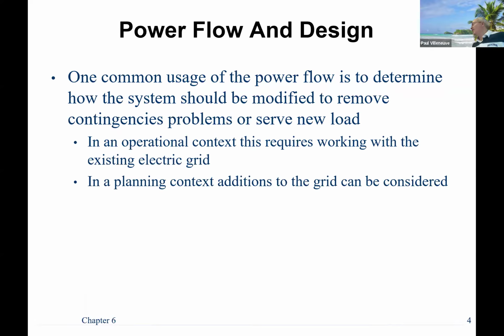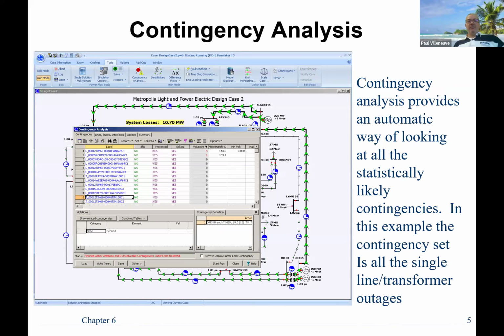So contingency analysis, this is really good because remember, contingency analysis is if we take the worst case system out, the system should still be survivable. How do you take a system out of service? You actually can automate the process, and you can see here, let's take out line 1 to 2. Let's take out line 3 to 4. Let's take out generator 1. Let's take out transformer 17.